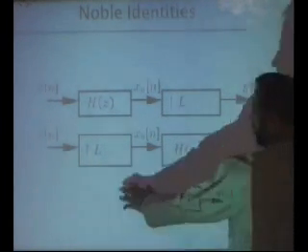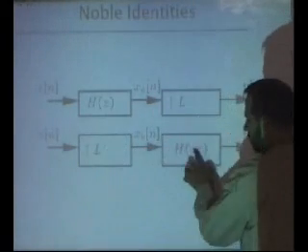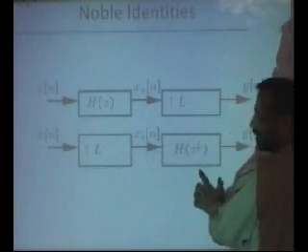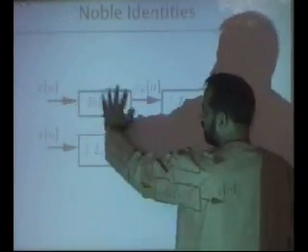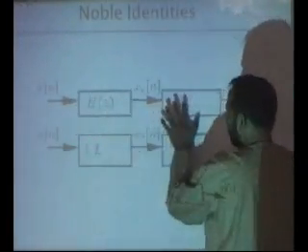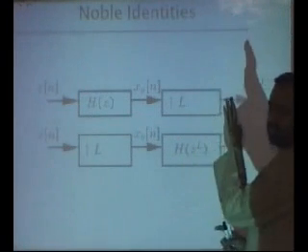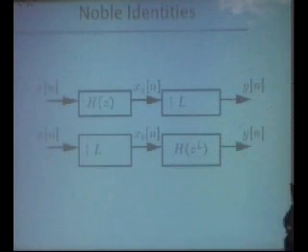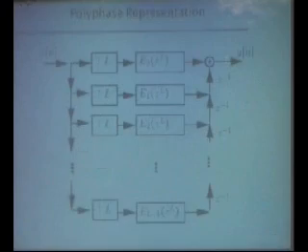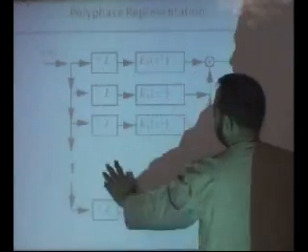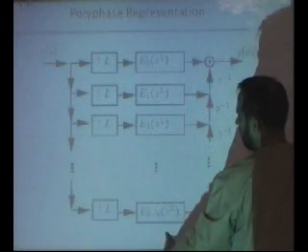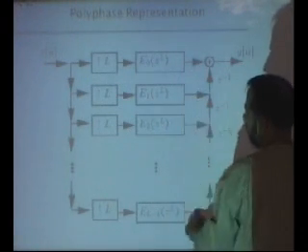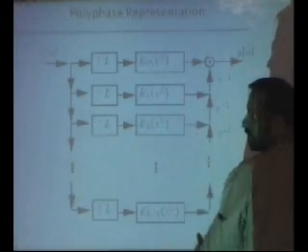If you have an interpolation and then a filter with several zeros, you change their location, so you pass it through a filter without zeros and then you insert zeros. This is what you apply here. So if you apply here, these will eat up all these z raised to the power L, and you have inserting zeros coming here.